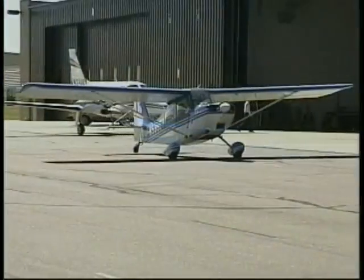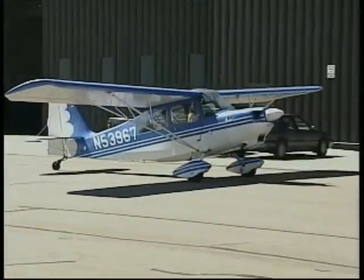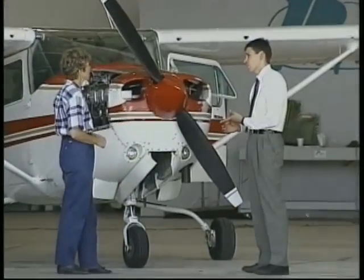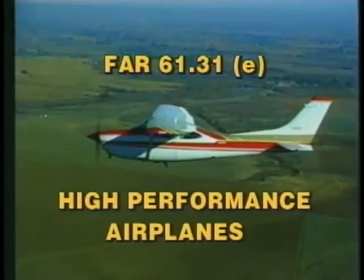As instructors, we can understand the importance of possessing sufficient experience before we are qualified to give safe and comprehensive instruction in a specific airplane. With that in mind, let's take a look at some additional opportunities for aircraft checkouts. The high-performance checkout is one more service you can furnish that will increase a pilot's knowledge, skills, and experience. FAR 61.31 defines high performance as an airplane that has more than 200 horsepower or that has retractable landing gear, flaps, and a controllable propeller.